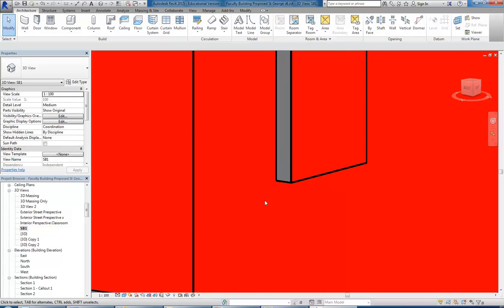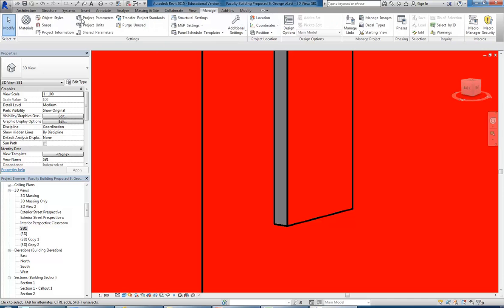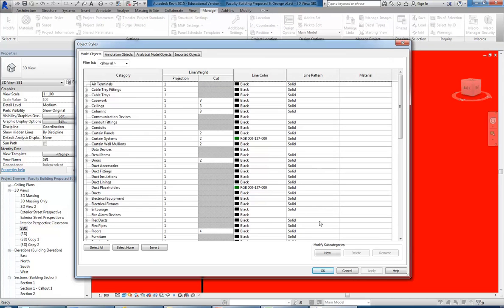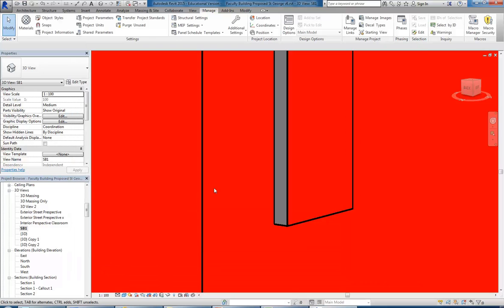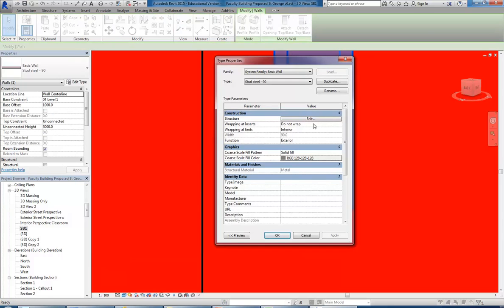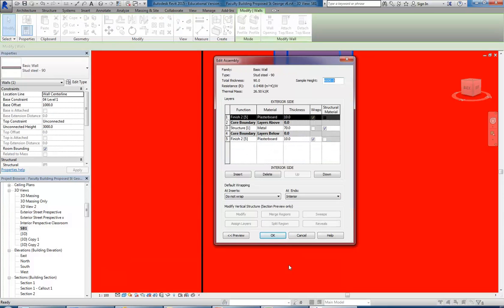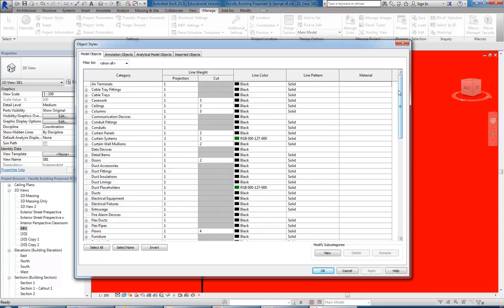You can set it if you're using the object styles, the way I mentioned earlier. You can go in and set options for your object styles to get some of the ends to wrap or to have a colour automatically. And I'll come back and spend a bit more time on object styles later as well, so make sure you realise that that option I showed you before, by category, which you will see come up quite often in here, is referring to the categories that you have in object styles on the Manage tab.